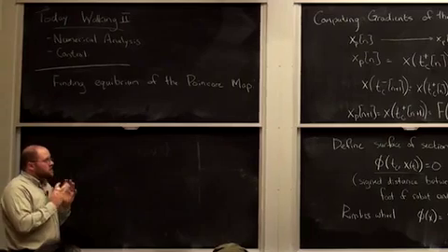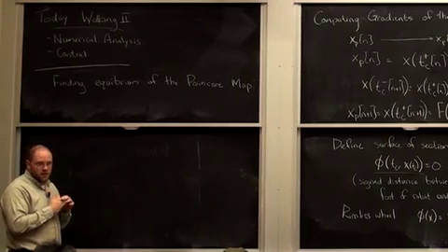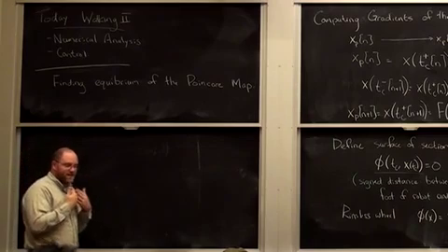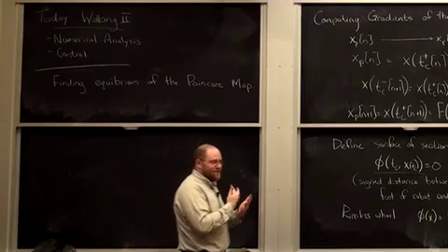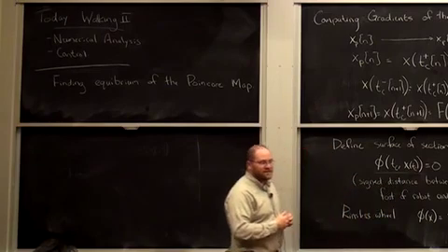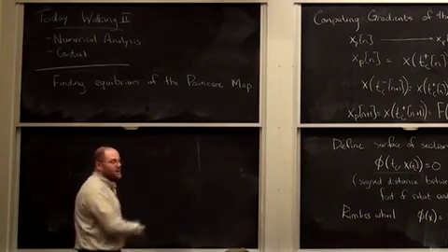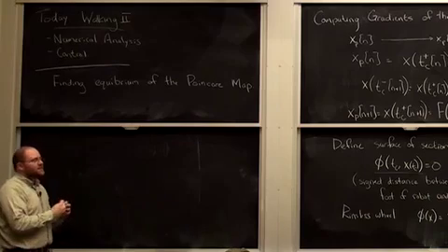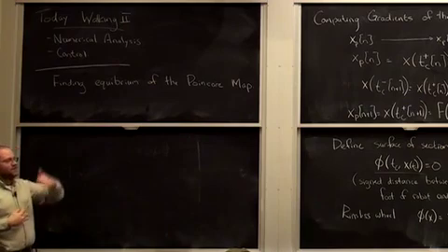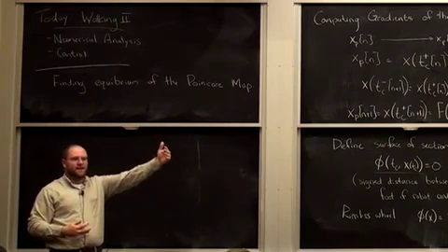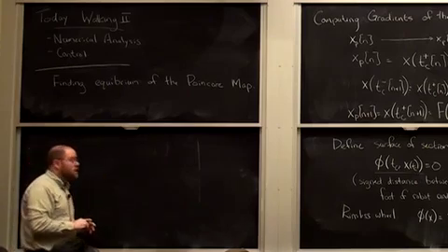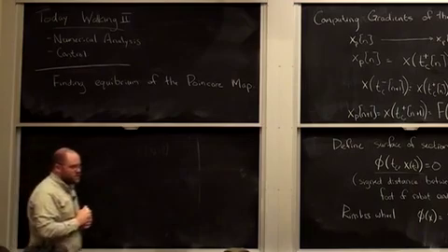But this idea of actually changing to a discrete time system is a bit empowering too. You can always do it. It's not that you only do it for walking robots. I could take any continuous time system, instead of looking at it at every t, I could look at it at discrete intervals of time. I could take a ball that I throw across the room. It has no impacts whatsoever. I could look at the system at x of time 0, then at t equals 1 second, x of t equals 2 seconds, and I could build a discrete time system from any of these continuous time systems. It's particularly nice to do it on these walking robots.